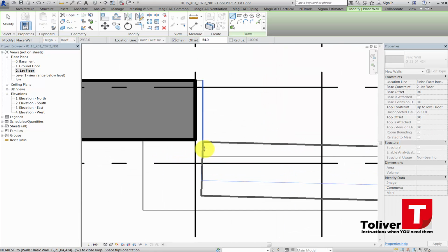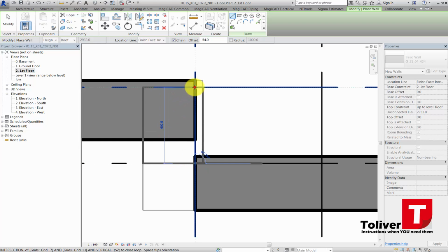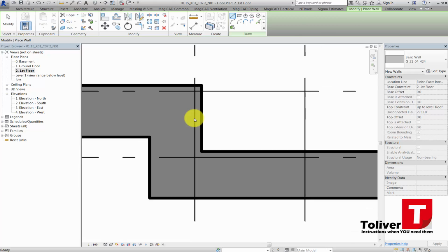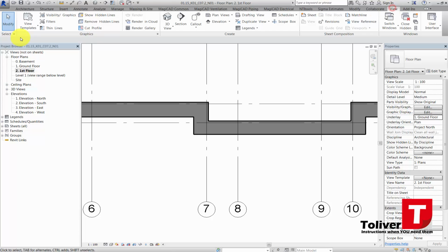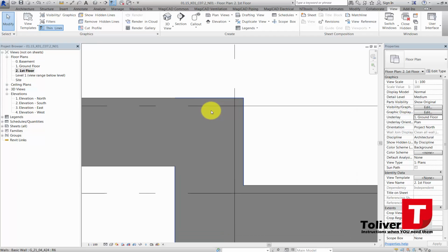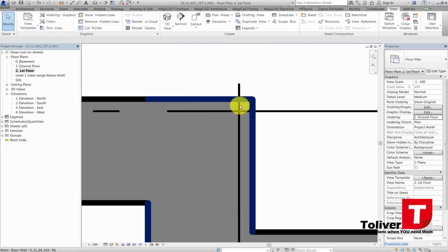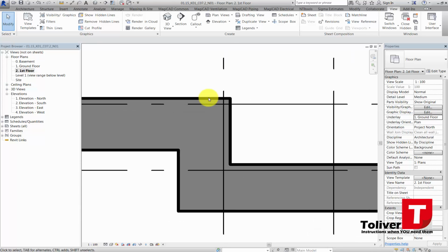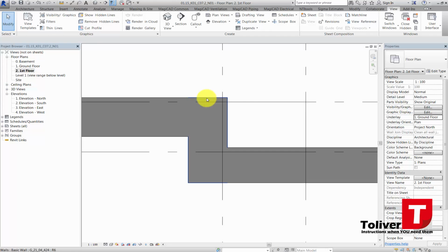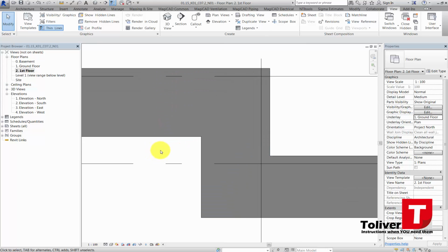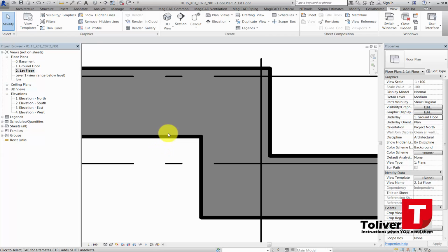And some people are kind of annoyed when they look at the lines because they're so thick that you're having a hard time looking at them. The way you could change them is by going up under view, and you have one here that's called thin lines. Once I click thin lines, the lines become thin, but thin lines, or the shortcut TL, actually shows you the line width, the thickness, when you print your project. So if you have TL or thin lines activated, this doesn't give you the true view. TL off shows you how it's going to be.